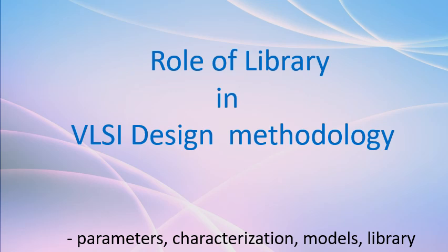In VLSI design, a library serves as the foundational database that holds pre-characterized information of logic gates. These libraries are crucial for design, simulation, timing verification, power analysis, and ultimately, successful chip fabrication. A library contains models of characterized CMOS gates with characteristic parameters. Parameters are generated through simulation or silicon characterization and stored in libraries. Libraries are critical to ensuring design accuracy, performance, and manufacturability.